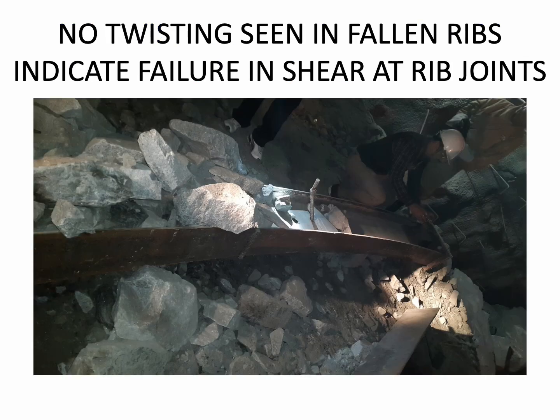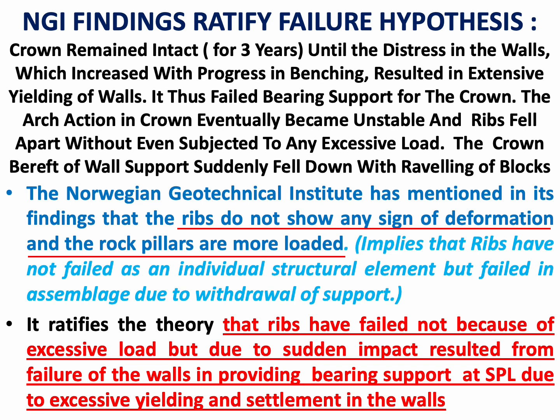No twisting was seen in the fallen ribs, indicative of failure in shear at the rib joints. So NGI also finds that the curvature of the ribs was intact. There was no twisting seen in the fallen ribs. That means the ribs would have failed at their rib joints under shear. NGI's findings ratify the failure hypothesis.